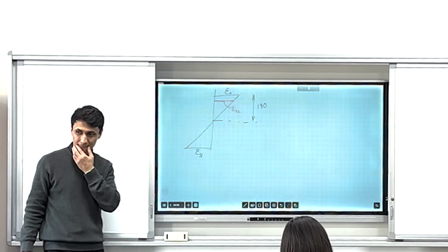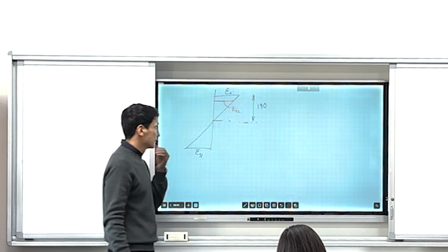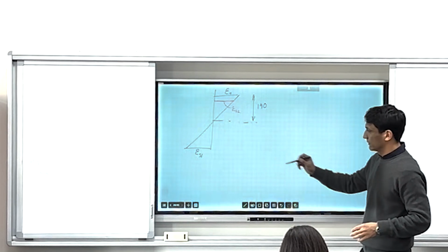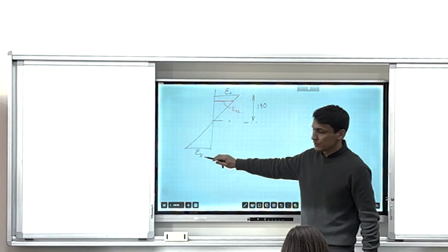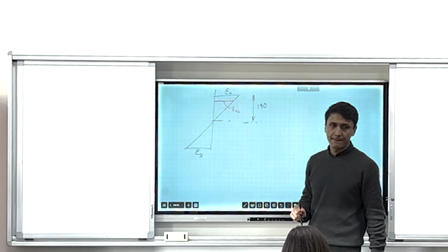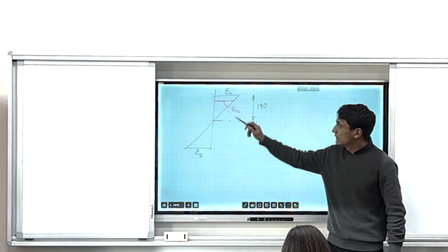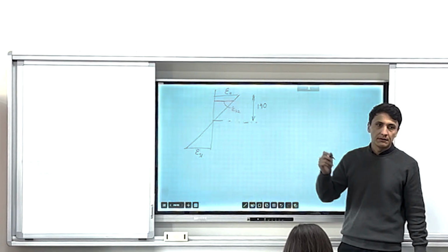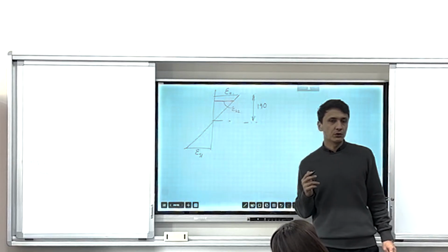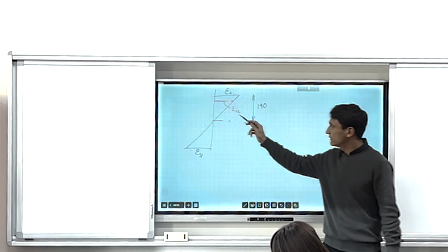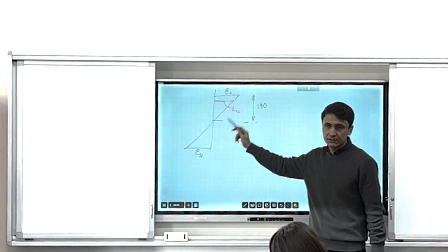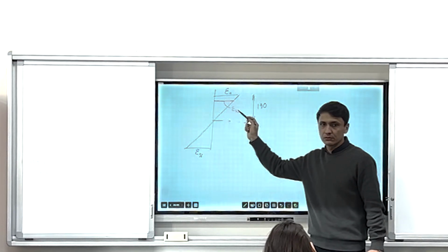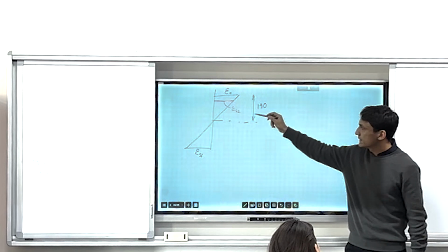Because it's between stress and strain? Yes. So now, the first thing that I have to do is to find epsilon s1. So now you see, I have epsilon s2, epsilon s1. But at the beginning, I told you that we are assuming top rebar to be yielded also. If it will be yielded, it would be same with this one. But it is not same actually. So I'm putting different epsilon s1 and epsilon s2. So now we're gonna find the stress at the top rebar.